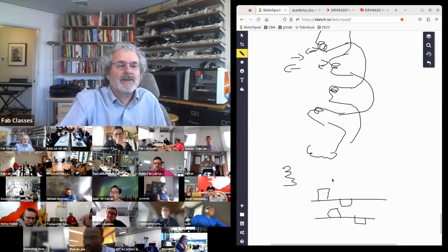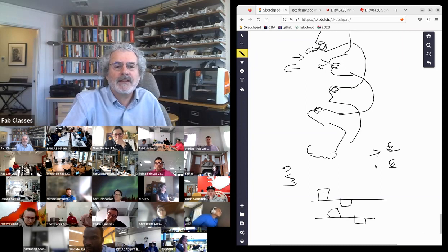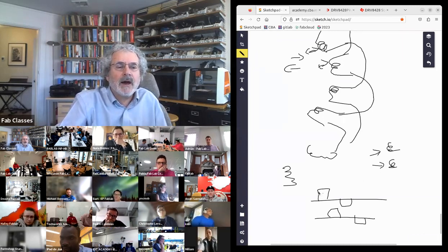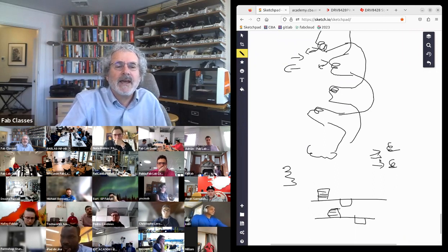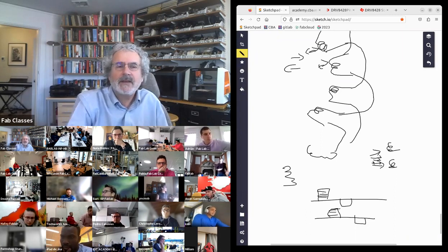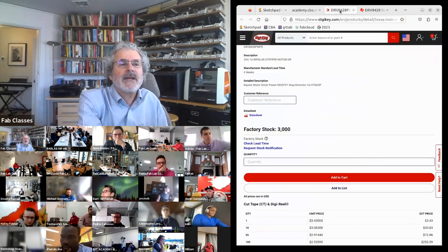And each time we make that transition, if you look at the coil winding, the stepper goes from being pointed to that coil to that coil. But what we can do is microstepping, where in steps we reduce this current, and in steps we raise that current. And so it means the stepper can make steps smaller than the coil winding. And so that's called microstepping.